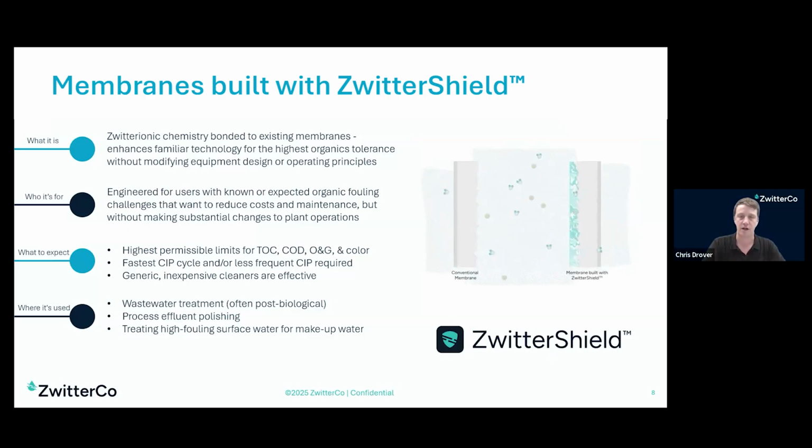The products using this technology in general have the highest allowable limits for membranes in their class against things like total organic carbon, chemical oxygen demand, oil and grease, and other organic components. These membranes also have faster, better cleaning outcomes, and they use fewer chemicals and cheaper chemicals to do those cleaning operations.